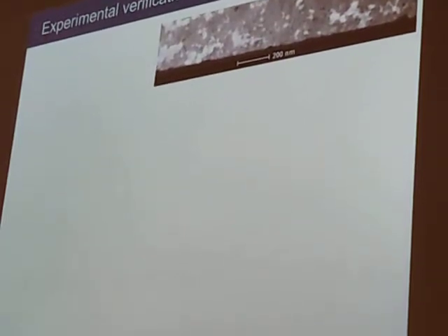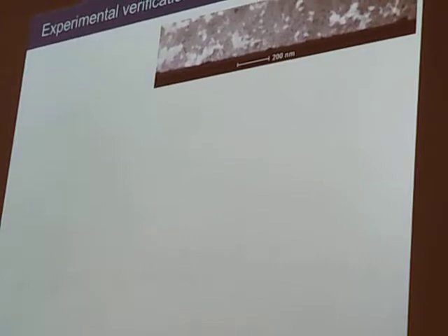The light white areas are gold, with quite a bit of germanium. The dark grey areas are germanium with a small percentage of gold in solid solution. But that exact mess is exactly what we want, because in order to get the effects to work over a broad range of temperature, we know the atoms must be in a broad range of environments, which we can induce by putting them under this very rapid quench.